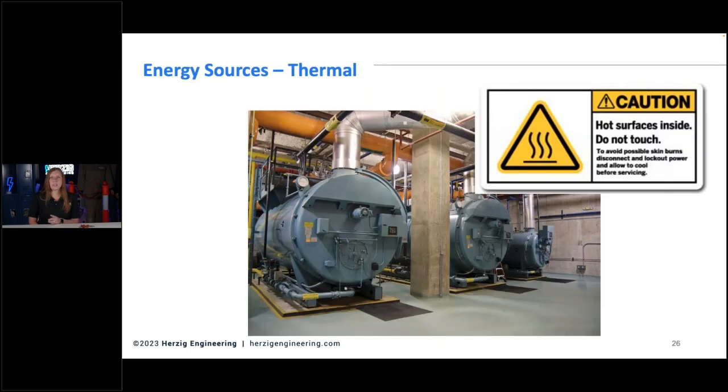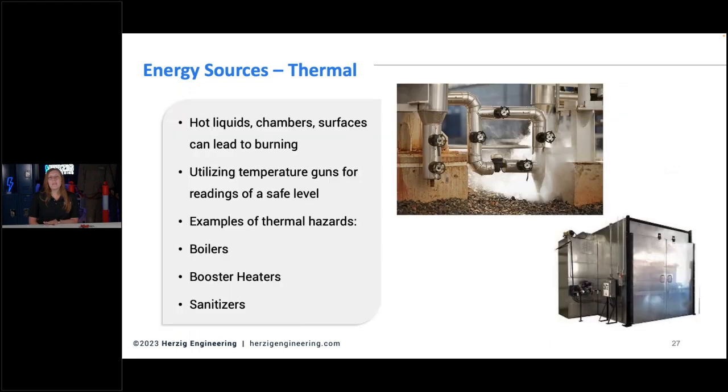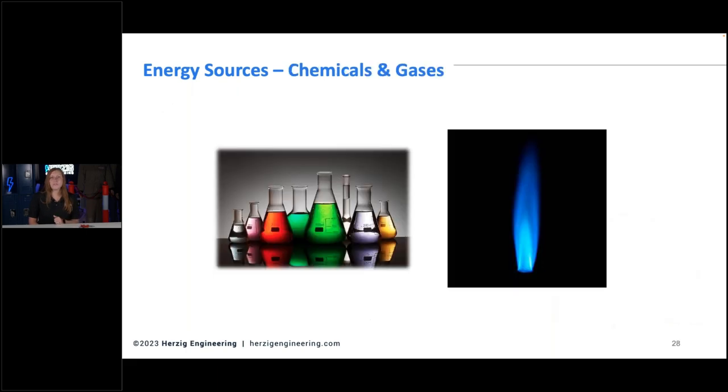Thermal is a little bit interesting. So oftentimes there's electrical, maybe a gas component with this, but it comes down to just it's hot. And so if you shut it off, a lot of times you have to figure out how long it takes for it to cool off before it no longer is a hazard. Like being burnt just from touching it or being too close to it even. So things like boilers, booster heaters, sanitizers, things like that. Maybe you even need to use a temperature gun. Instead of setting a designated time, you would need to, in your procedure, say after so long, use your temperature gun and make sure it's below a certain threshold for safe levels.